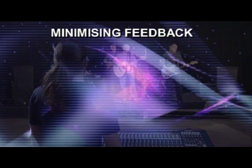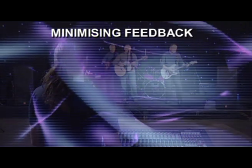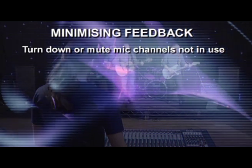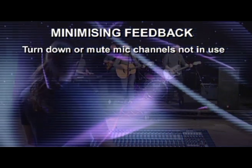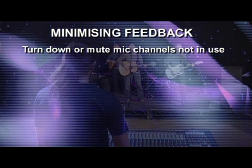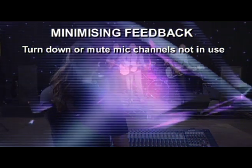Feedback is the ever-present hazard in live venues. Here are some ways to minimize the problem. Turn down or mute any microphone channels not in use. Not only will this reduce feedback, but it'll stop the microphone picking up spill from the backline and stage monitors, and you'll get a clearer sound.